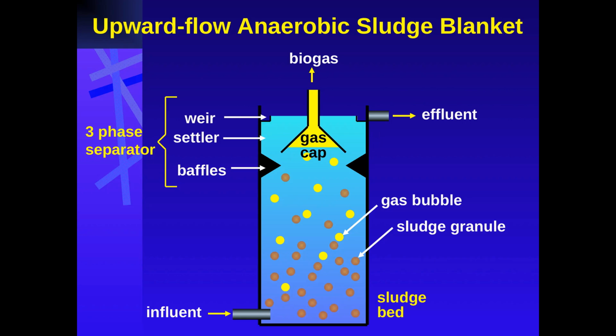This image demonstrates the superior settling properties of granular sludge compared to flocculent and dispersed sludge. The dense, compact nature of the granules allows them to settle rapidly, which is crucial for maintaining a high biomass concentration in the reactor. This high settleability is a key factor in the high performance of UASB and EGSB reactors.